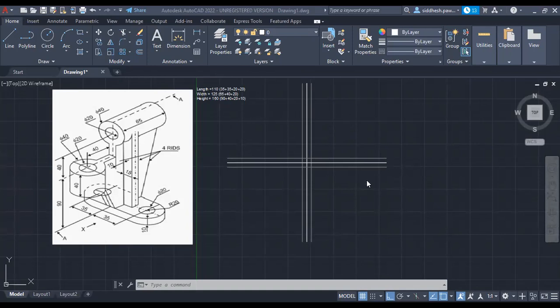यहाँ पे होगा front view और यहाँ पे होगा top view. I hope everyone is aware कि how it is being decided. हमको कौन सा view दिख रहा है? If the observer is standing here, उसका right hand यहाँ पर दिखेगा. So this is the right hand side view, which is being placed on the left hand side of the front view. Front view इधर आएगा तो उसके left में इधर आएगा, and then just below the front view will be the top view.